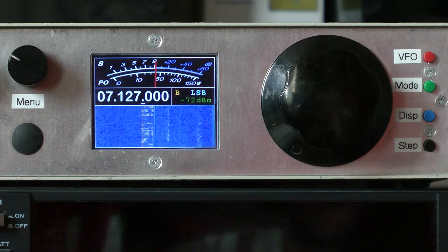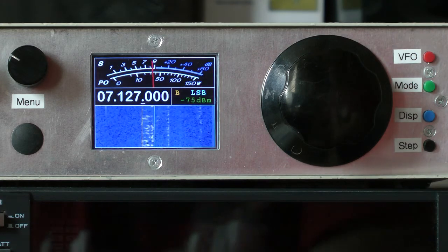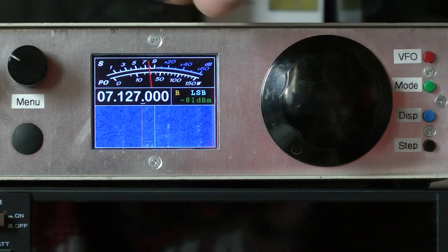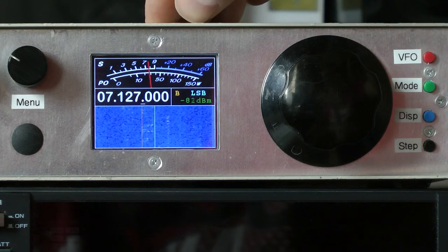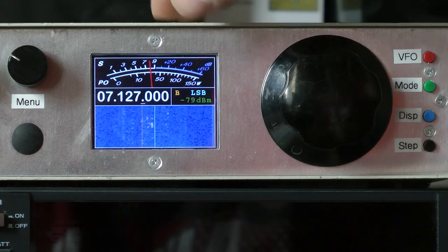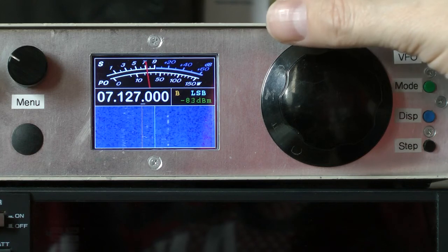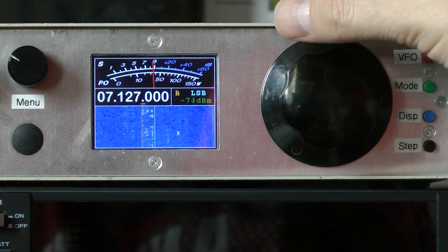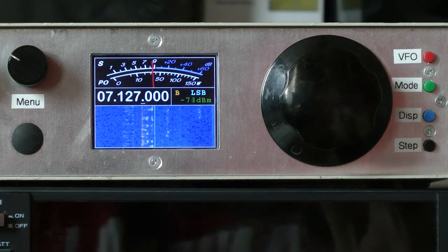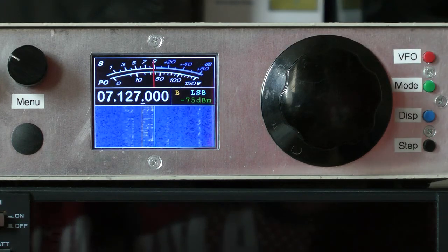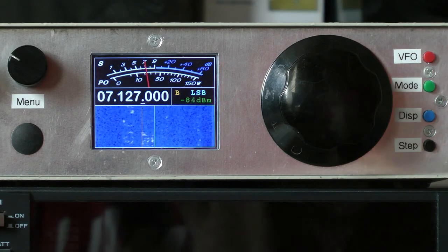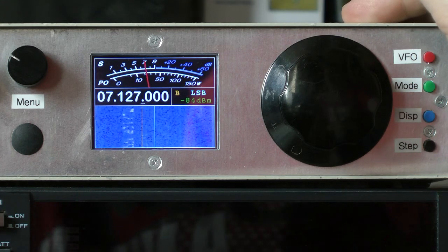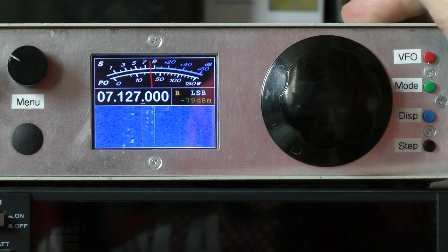So overall, the performance of this receiver I think is exceptional for the money, the cost of components. The adjacent channel performance is superb. The filters that I'm using have an 80 dB stop band, which is very strong rejection of signals either side. The bass response of the receiver is very good because of the steep skirts on the SSB filter. You can place the VFO position quite close to, well, it's around 100 Hertz away from zero.